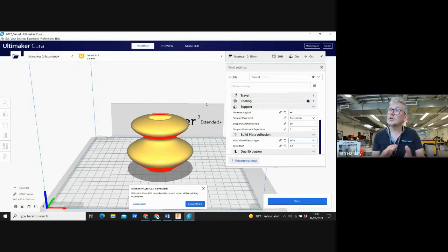And that material is PVA, which you'll probably know as a kind of wood glue, which is, of course, water soluble. So for particular models that are quite complex, we can put them in water, and the support material just basically dissolves. It just washes away over time.